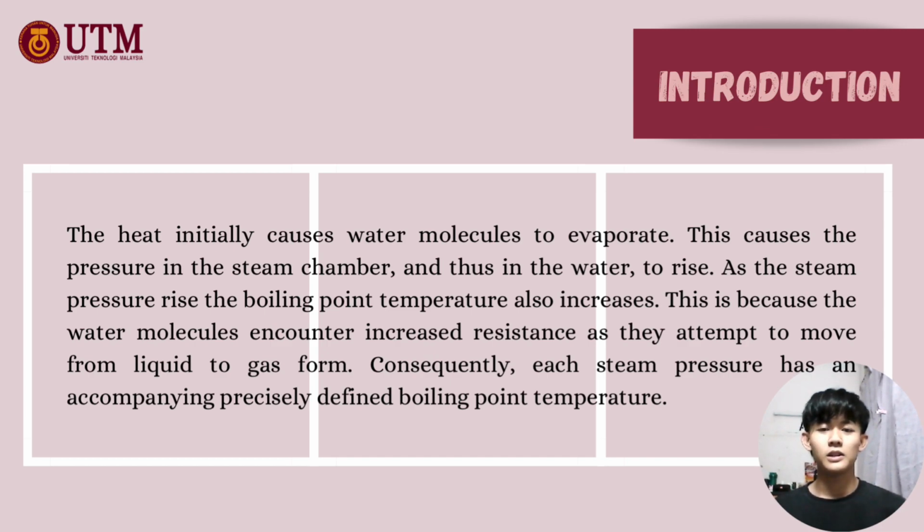The heat initially causes water molecules to evaporate. This causes the pressure in the steam chamber, and thus in the water, to rise. As the steam pressure rises, the boiling point temperature also increases. This is because the water molecules encounter increased resistance as they attempt to move from liquid to gas form. Consequently, each steam pressure has an accompanying precisely defined boiling point temperature.